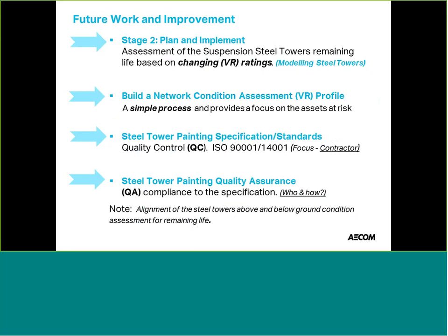You model the structure in PLS Tower, and you start to work out the levels of deterioration of certain members, from the top working your way down to the base. As we mentioned, a lot of the structural issues and deterioration were in the top half of the tower, of a suspension tower, which is only supporting strings. So it gives you an opportunity to look at how you want to manage that risk and how long you can defer the replacement cost.